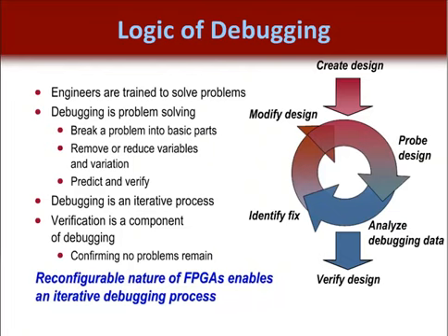The design can then be changed, resynthesized, and re-implemented before the FPGA is then reprogrammed. This iterative debug process is possible because of the reconfigurable nature of the FPGA. This speeds the entire design verification process and gives the engineer a great deal of confidence that his design is operating properly and reliably.